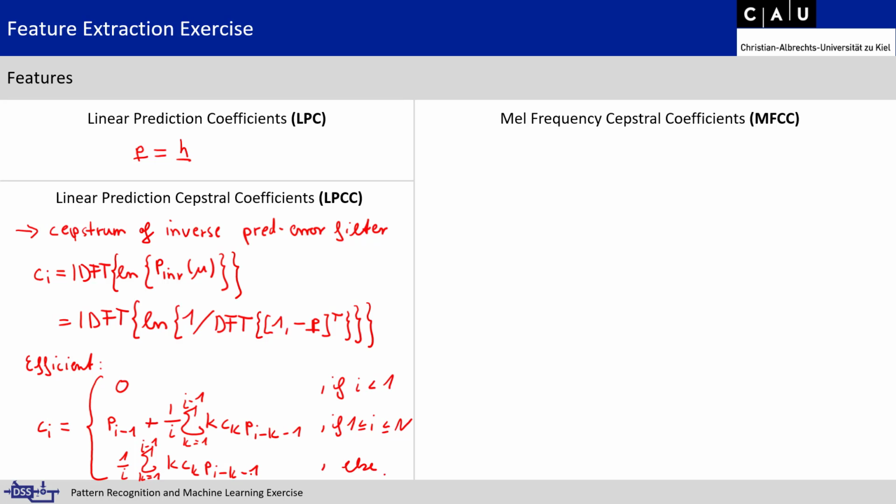And the first step, or I want to say 0 step, is windowing our signal. Usually we assume that we have already a section of our signal for a DFT, but here you can play like always with the window function. So this is sort of optional, so that's why it is 0. And then, like I've already said, the first step is performing a DFT, so we go into the frequency domain. But with MFCCs, we're looking at power. So we're then taking the magnitude square of our DFT values.